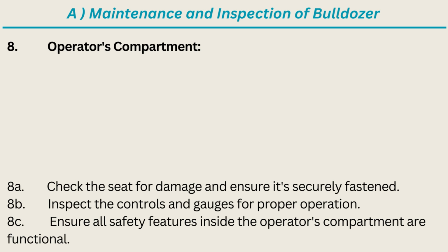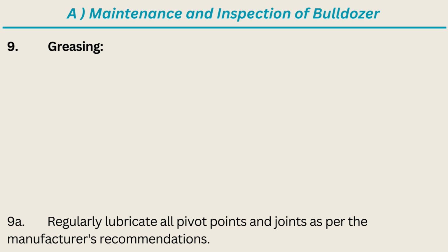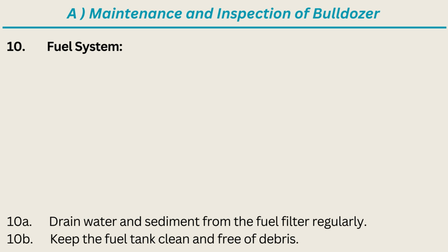8B. Inspect the controls and gauges for proper operation. 8C. Ensure all safety features inside the operator's compartment are functional. 9. Greasing. 9A. Regularly lubricate all pivot points and joints as per the manufacturer's recommendations. 10. Fuel system. 10A. Drain water and sediment from the fuel filter regularly.